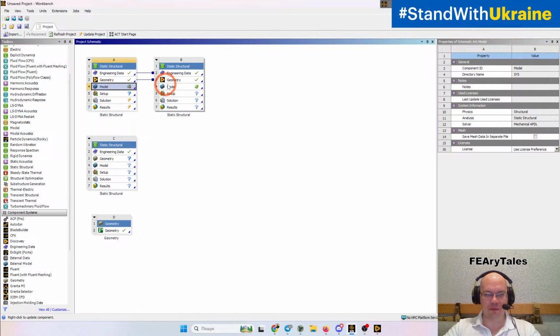It doesn't have a connection through the model, but it has a connection through the geometry. Let's take a look. Maybe the new object will work without those errors. If we have this error again, we need to restart Ansys Workbench and create the new model.